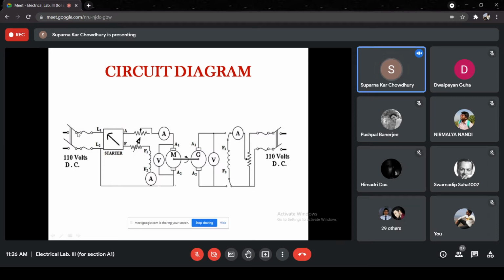So VI input here minus I square R of the motor will now give us all the losses of the motor plus windage and bearing friction loss of the generator, brush friction loss of the generator, plus the core loss of the generator. So from this run, by subtracting the other losses already calculated, we can separate out the core losses.